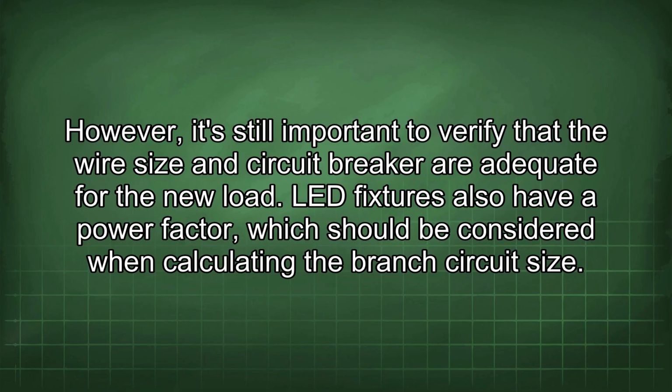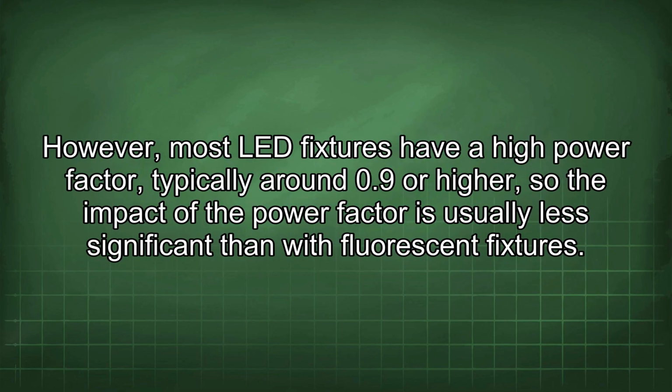LED fixtures also have a power factor, which should be considered when calculating the branch circuit size. However, most LED fixtures have a high power factor, typically around 0.9 or higher, so the impact of the power factor is usually less significant than with fluorescent fixtures.